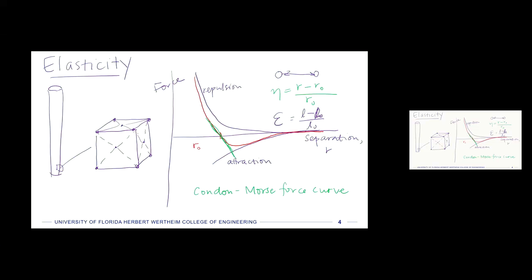And so from this kind of understanding where we can draw that tangent line, that there is a coefficient that describes the relationship between those two, we can say that the force is proportional to strain, or the force is proportional to elongation for any component or at the atomic level of this crystalline lattice. And that's only in 1D, right? So that's just atoms or maybe a component in 1D.